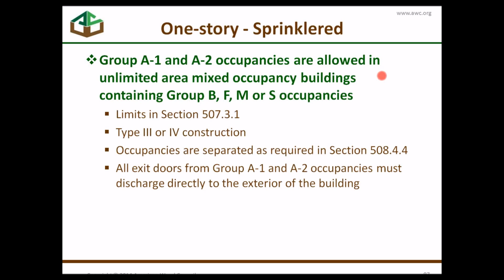In these use groups, you're limited more traditionally by what you can do with wood construction. That is changing. What you can do with wood construction, of course, is changing due to the introduction of new and innovative mass timber products, such as CLT, and so forth. We might touch on that a little bit later. But unlimited area buildings are permitted for these use groups.